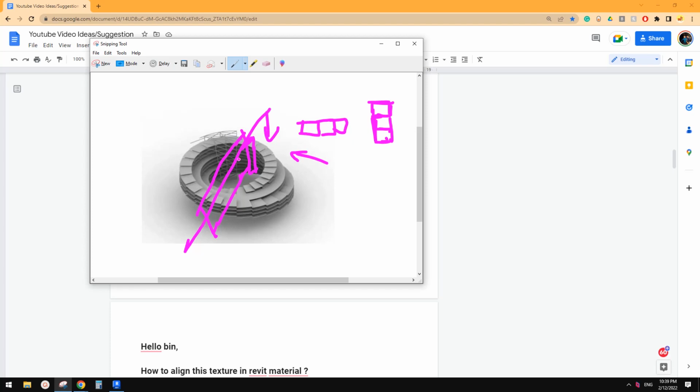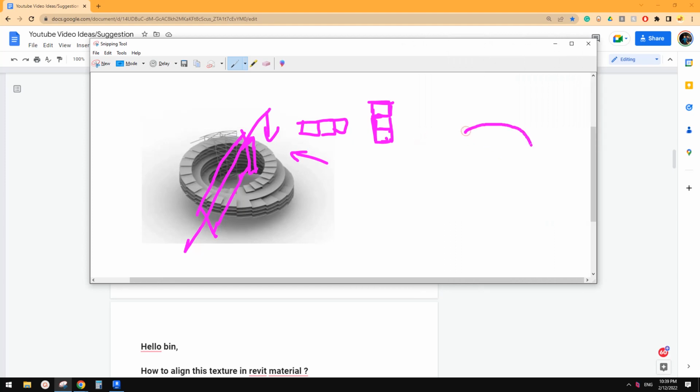So what we can do is, for these 3, we can use one same circular path, and then we can just use different profiles. So for example, for the top one, it goes all the way up, from this top to this. So we can have a profile in this location. When it's in this location, it's on top, and then when it goes to here, it goes to here. The one in the middle stays in the middle, and the bottom one sits in here. So then we have this profile and this profile, and they can share the same path. Okay, so let's do it.